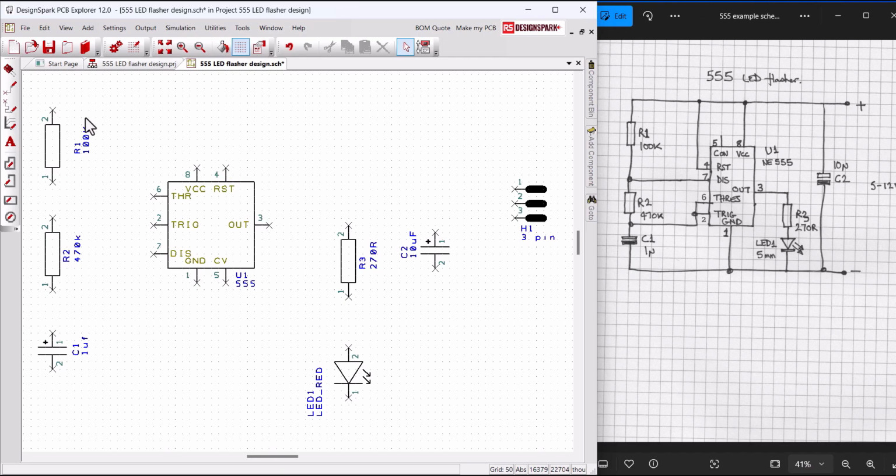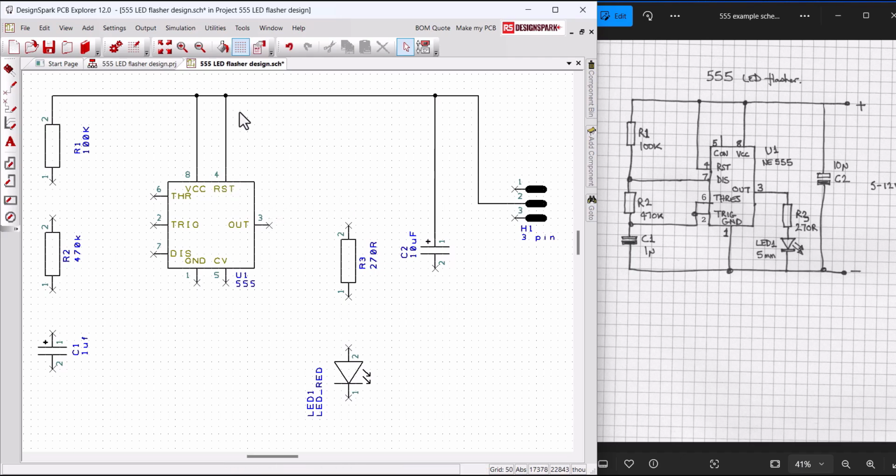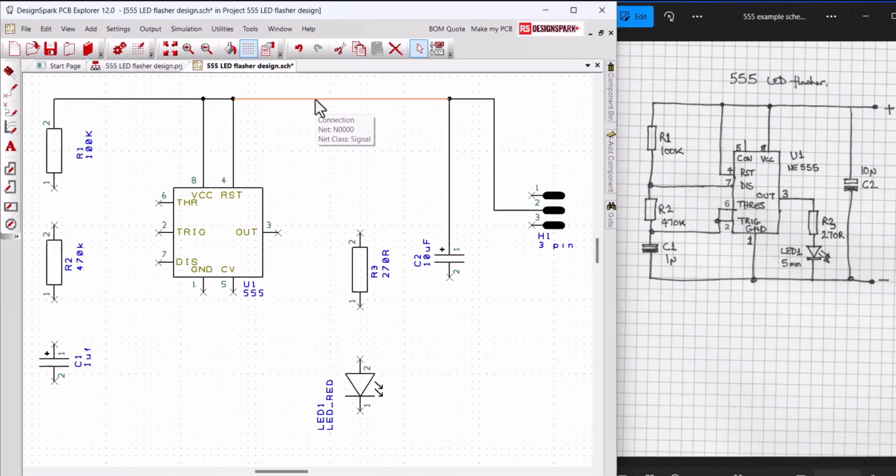Now, to wire up the nets, click the X on the component and drag away to draw the net. Click to fix the position at any point and click on the X to connect a destination pin or onto another net. Using the mouse over or highlighting a segment of a net, the net name is displayed.